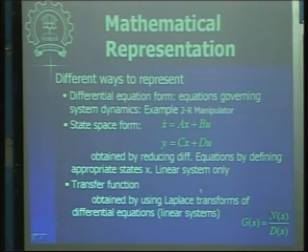So you first take the Laplace transform of the differential equation, then separate out output and input and take their ratio. Name it the transfer function and find the numerator and denominator polynomials. This is how you proceed to find your transfer function.